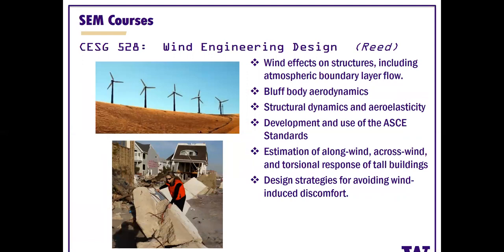Wind engineering, likewise, goes beyond what most engineers necessarily do in practice, which is rather than use prescribed building code wind loads, let's get them ourselves. Let's do computational fluid mechanics, and let's first try to understand the mechanics of wind loading, and then use our understanding to get loads on complicated structures for which we don't necessarily trust the building code standard equations that are given.